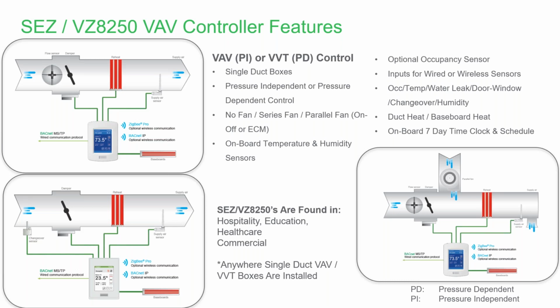And in particular, if you have any applications where there are the older Trane VAV boxes in a pressure-dependent application that have a worm drive, and it's a cone that's built inside of the box. So essentially, you can't replace the damper actuator, but it's working great, and you need to replace the controls for it. This particular product is a perfect fit for it, and we've seen a lot of customers having a lot of success in upgrading 30-year-old systems to something that is 21st century, right, with this particular product. So that's a pressure-dependent application.